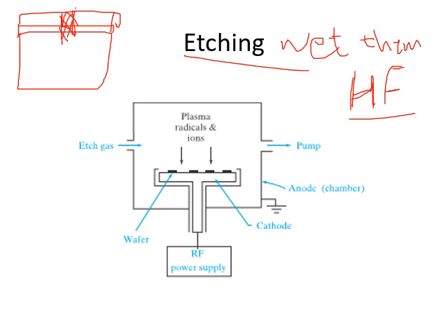So the other part should not be affected by this etching. Say if you are etching this part and even side by side some other parts are also being etched, then it goes waste. So that is called selectivity. So this dilute HF, it is just a chemical liquid, right? So that had a good selectivity. Means wherever you wanted the etching to be done, only that was done by the HF, right?